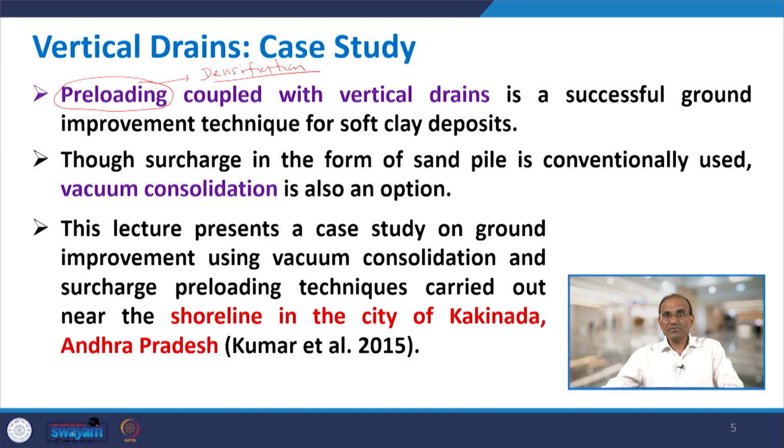Though surcharge in the form of sand piles is conventionally used, vacuum consolidation is also an option. This lecture presents a case study on ground improvement using vacuum consolidation and surcharge preloading techniques. So, two techniques will be used. One is called vacuum consolidation and another is surcharge preloading. And this technique has been carried out near the shoreline in the city of Kakinada, Andhra Pradesh, and this has been published by Ganesh Kumar et al., which we have just discussed.